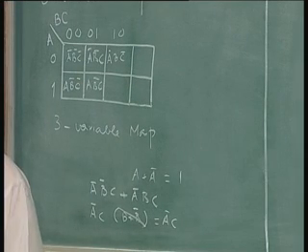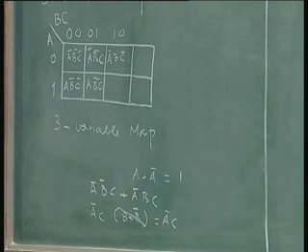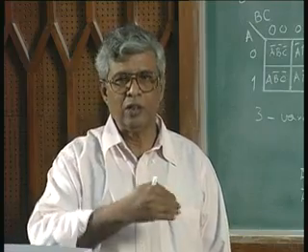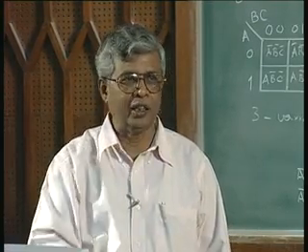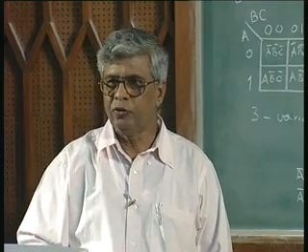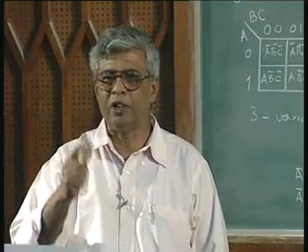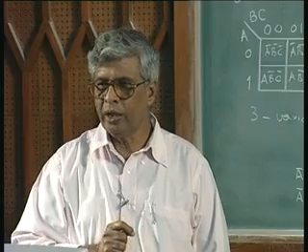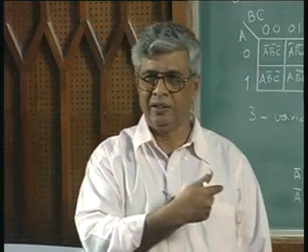Between B and C, I should let only one of those variables change from cell to cell, from one cell to the next cell, either in the horizontal direction or in the vertical direction. If you let only one variable change and the other variable keeps its value, then I will be able to combine it with the previous cell.